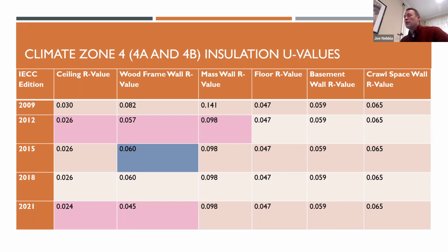So for R11 more insulation, you're only getting an incremental, a small change in the U factor target for that attic. And I think you'll find that the UA calculation favors being able to be flexible on the attic insulation by making some small changes in the building envelope, if that R60 is a problem for you. I know some builders who do R60 already, but that is a change for what the majority of builders are doing in climate zone 4 now.